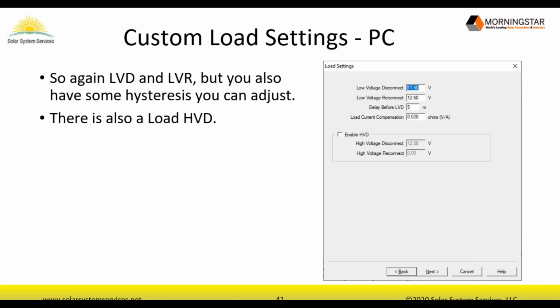The only thing you have to be careful with on that battery voltage is you want to make certain you're still within charging parameters for the batteries. If you make that too low, you may not be able to recharge your battery correctly. So just be careful using that. You might not want to set that at like 27 volts if your battery wants to be recharged to 28 or 29 volts, that would not be good. But setting it to a max of 30 is probably okay. So just double check with your battery manufacturer with regards to the max voltage before you start messing with that setting too much.